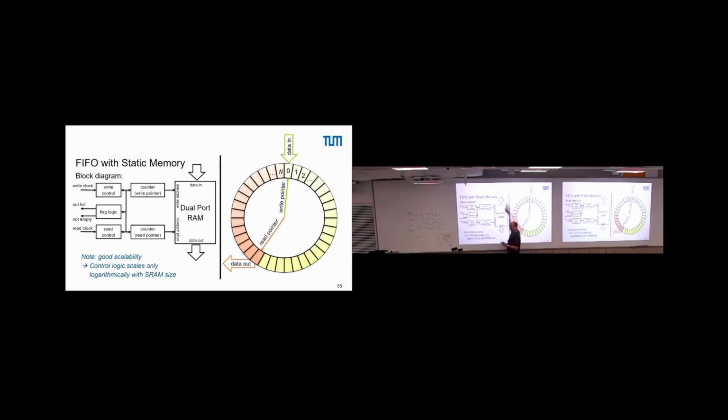The reset is triggered by the read domain, because you read something, then it stops being full, right? And this read-triggered signal is evaluated in the write domain because the write domain needs to know if it's full or not. Make sense?